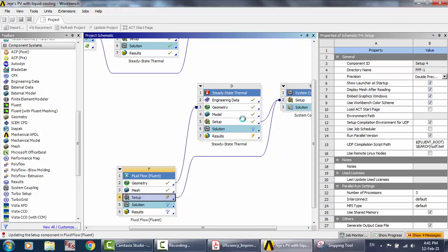The only difference here is the convection faces, 10 faces, because we added 4 more faces. We had 6 faces, and not considering the inner faces, which are 2 faces, so we got 10. And of course we changed the face that receives the solar flux.